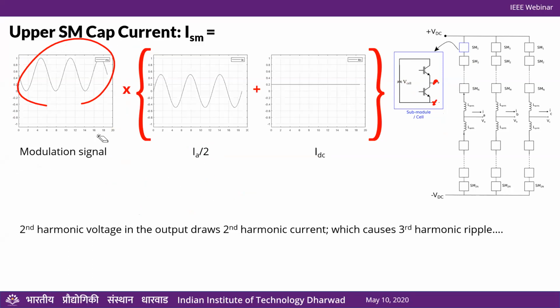So what ends up happening is that when the capacitor voltage was DC, everything was fine, no problem. Or if your capacitors are very, very large, no problem. The ripple doesn't appear anywhere. But when your capacitors are finite, then that ripple will now be multiplied with your duty cycle and appear here. So now your output voltage consists of a second harmonic voltage. Third harmonic, obviously, will also be there. And that second harmonic that appears here is like an additional voltage.